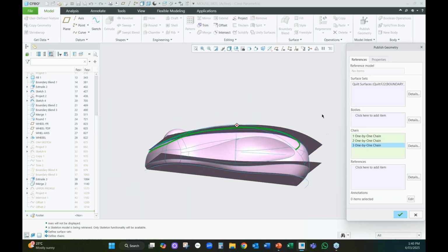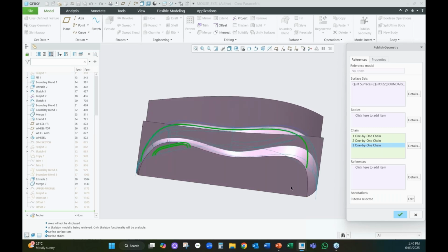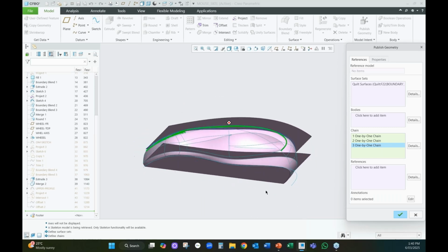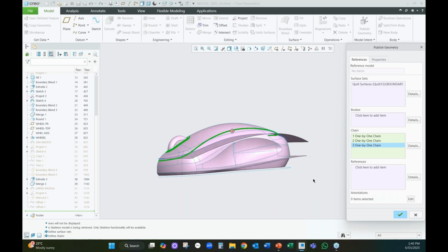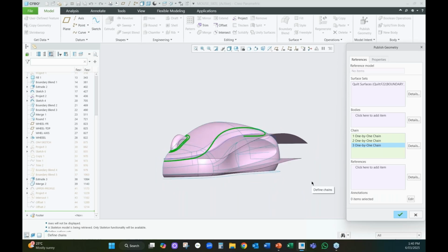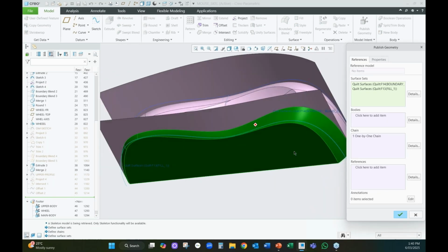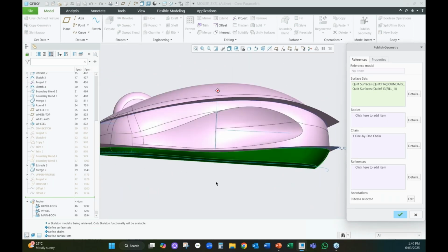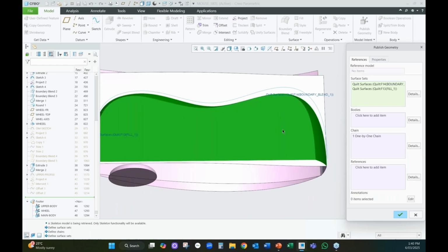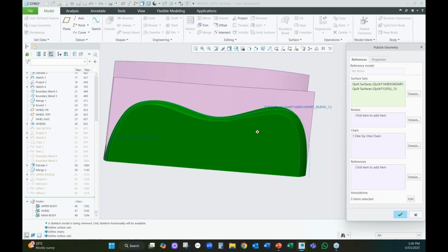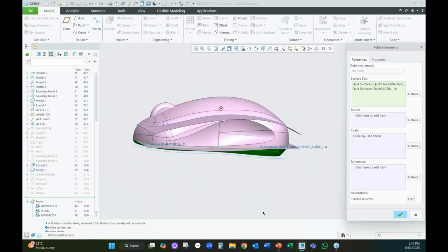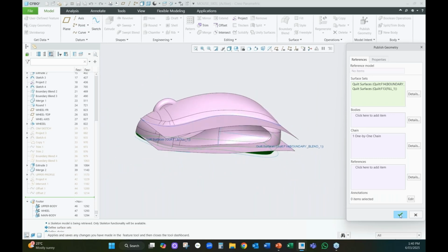This published geometry, being the upper part, doesn't need to be, I guess, overburdened with any geometry for the bottom of the product, because it's just totally unrelated to this part. Likewise for the bottom, if we've got lower body, if I highlight that, this is just selecting the geometry for those lower body portions. As you can see though, I don't have any feet or any part line or any scallop for the battery in this higher level, and I'll explain the reason for that in a moment.